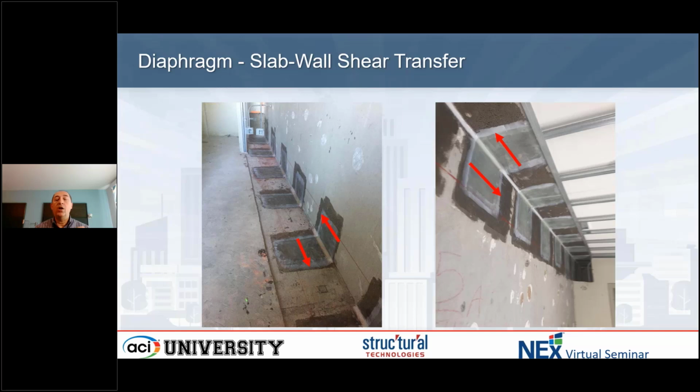So this is a building in New York. The design on the East Coast is controlled many times, depending on the location, for high rise, of course, by wind, rather than seismic, which controls the design on the West Coast. So a lighter layout, that's why you see strips at larger spacing. Glass was able to achieve this load transfer. Another application, I did not include a photo, could be a complete coverage from end to end with carbon FRP, again, bidirectional plus minus 45 degrees to transfer that load.